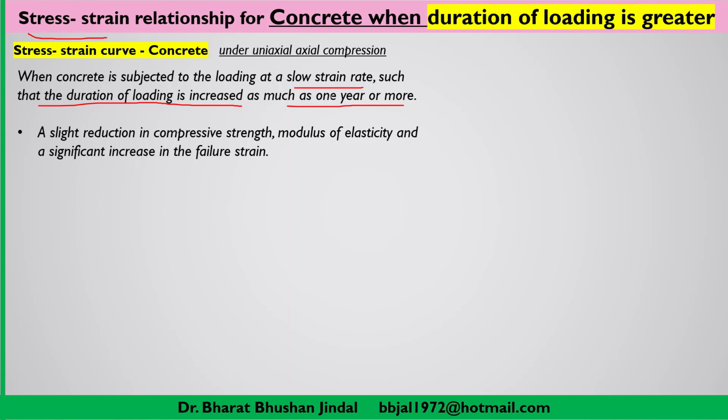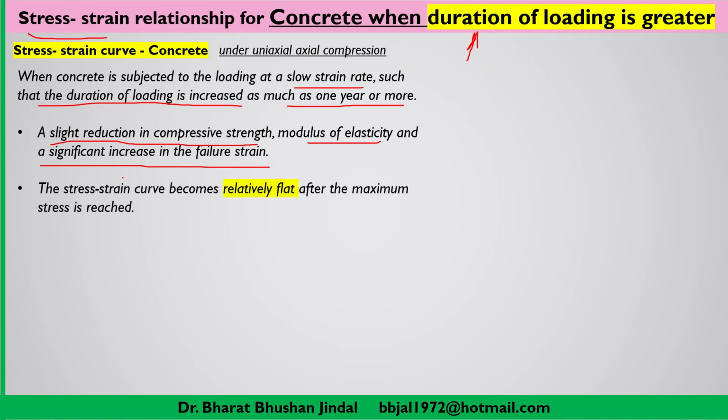When you draw the stress strain curve, when the load is acting for a larger time period, you will find a slight reduction in the compressive strength and modulus of elasticity, and a significant increase in the failure strain. The stress strain curve becomes relatively flat after the maximum stress is reached.